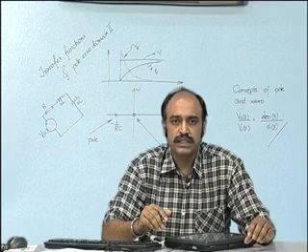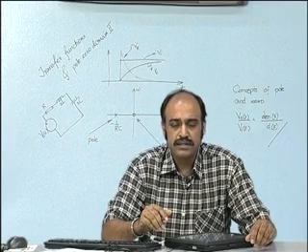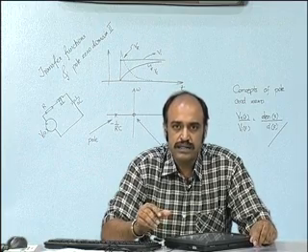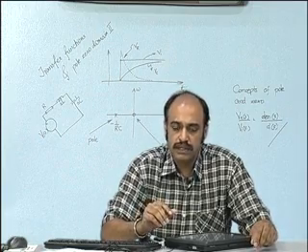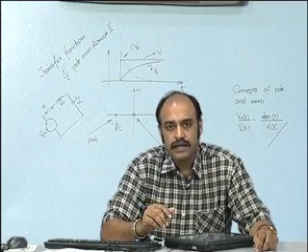Basically the transfer function is C (sI minus A) whole inverse B plus D, that is, using the A, B, C, D matrices as the input matrices you can obtain the transfer function. We will see some of those examples in MATLAB today.